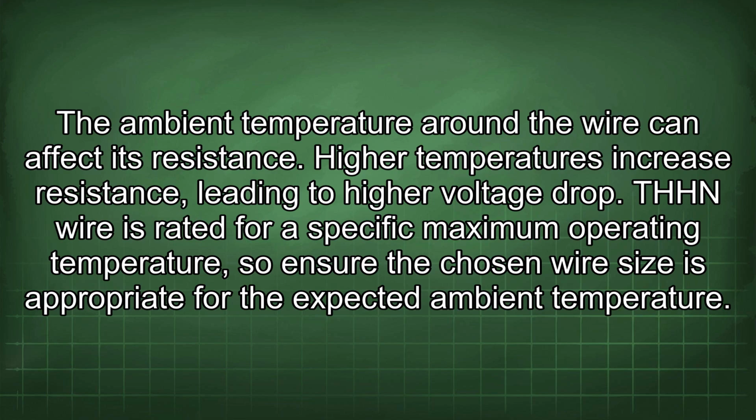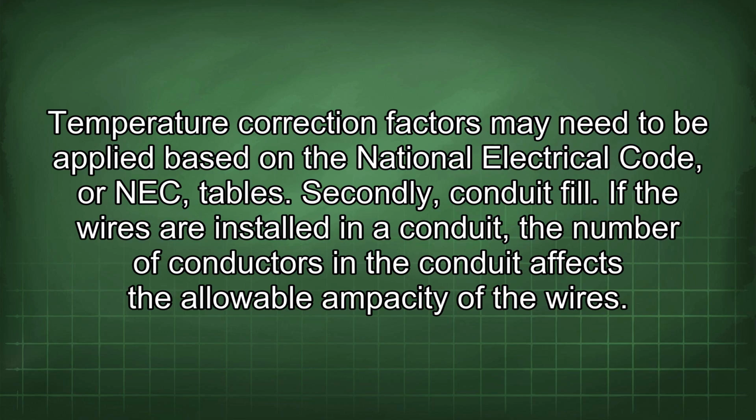Higher temperatures increase resistance, leading to higher voltage drop. THHN wire is rated for a specific maximum operating temperature, so ensure the chosen wire size is appropriate for the expected ambient temperature. Temperature correction factors may need to be applied based on the National Electrical Code or NEC tables.